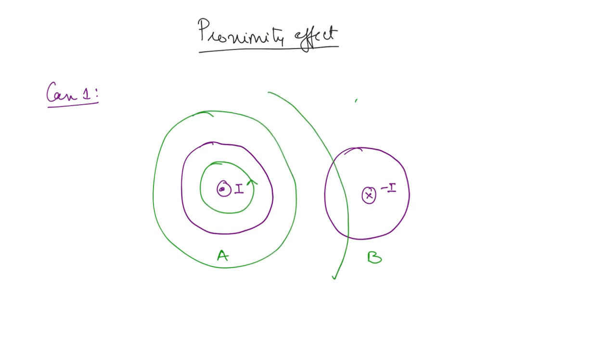And on the other conductor also they are going to have an effect. Now since this is an alternating current, the magnetic field is also going to be alternating, right? So it is a time varying quantity. When a time varying magnetic field is present, what will happen to the charges that are present in conductor B? They are going to experience force, right?